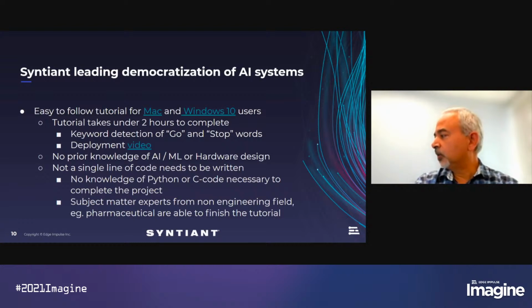And I'm assuming that you're not confusing it with the M0 which is also present in the NDP101. So yes, there is another M0 present in the NDP101, and its job is really to take the data from the neural network, post-process it, and provide interrupts, etc., to the host processor. So I hope that answered your question. Otherwise, you can reach me or you can ask a follow-up question.